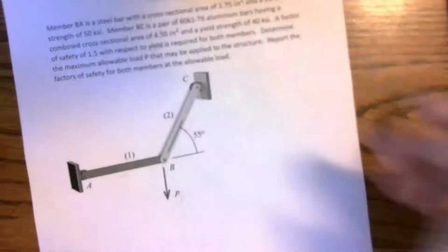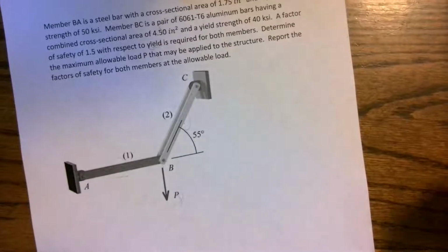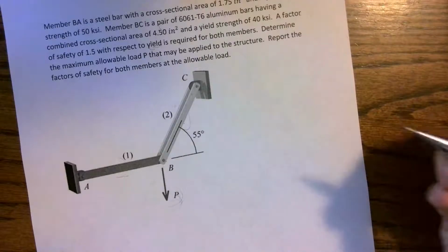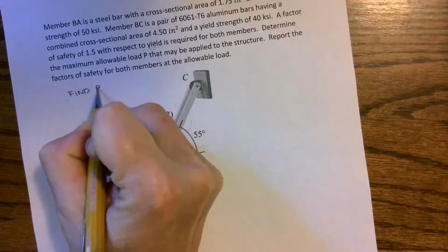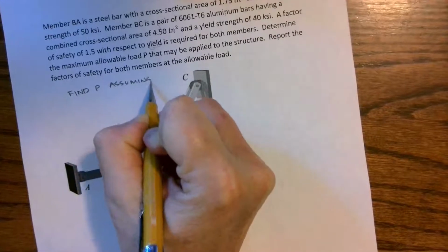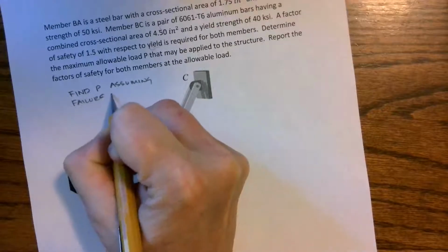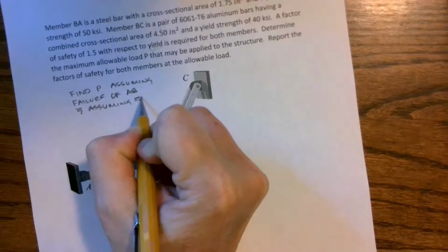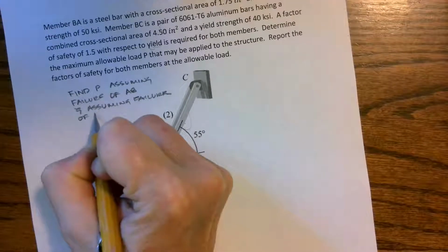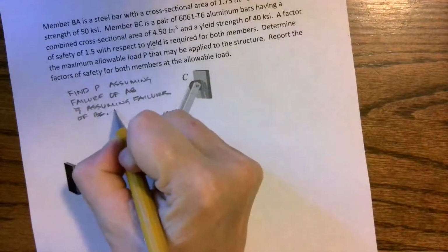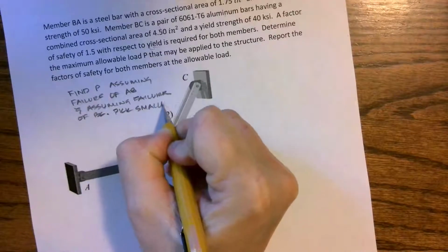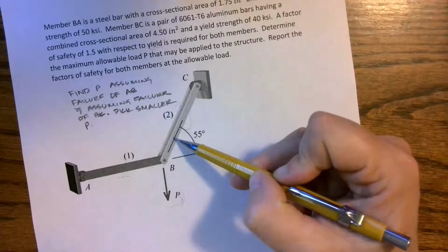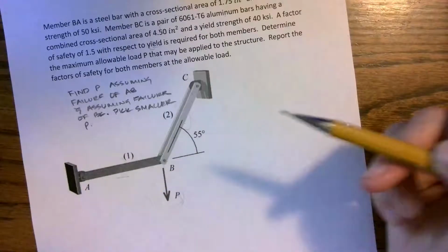So we've done several of these kind of work backwards problems. If you need help doing that, there should be still the video in statics review that's working through the cable system backwards, okay? So we want to find P, and we are going to have to assume failure of AB and assume then failure of BC, and then we're going to have to pick the smaller P, because we don't know, because they're different materials and they have different areas and they have different modulus and they have different yield stress. We don't know which one is going to end up being limiting.